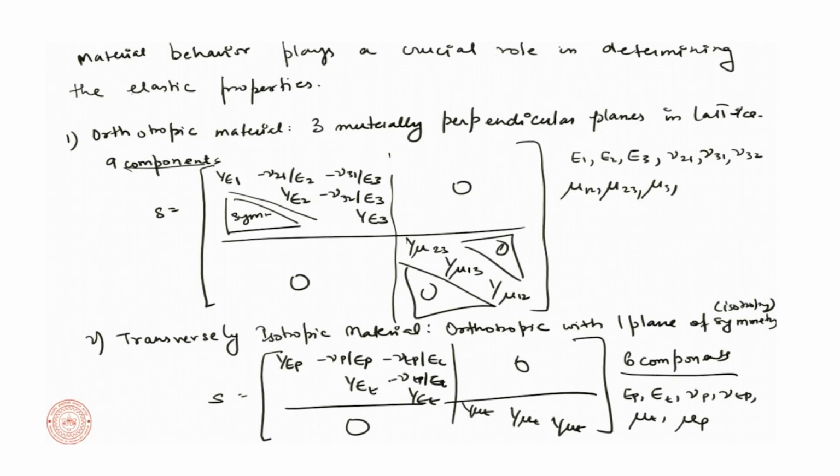So, this should be mu T, the perpendicular plane. Okay. Please do check this one more time, and always refer to the Applied Mechanics of Solids by Allan Bower. Okay. So, there should be 6 components that are required to define a transversely isotropic solid.